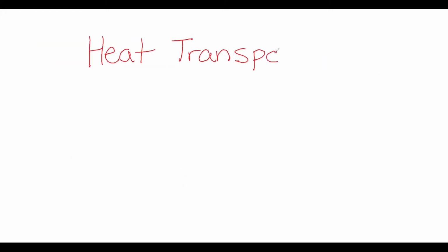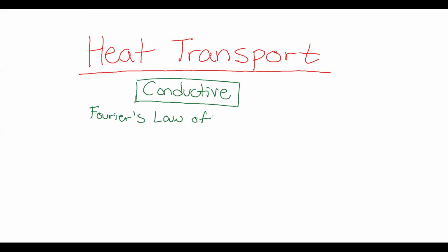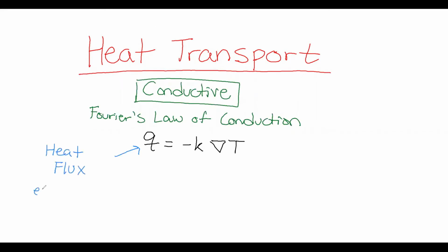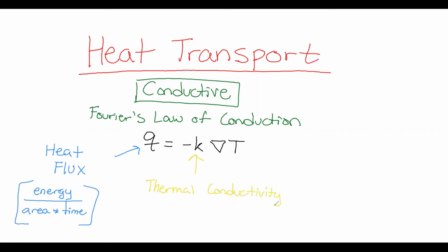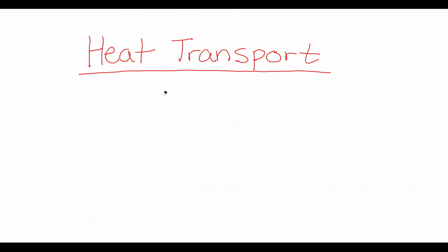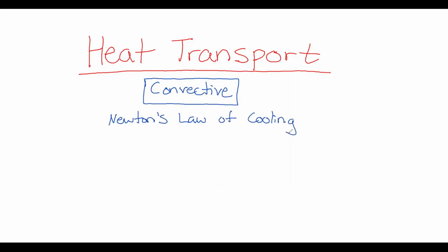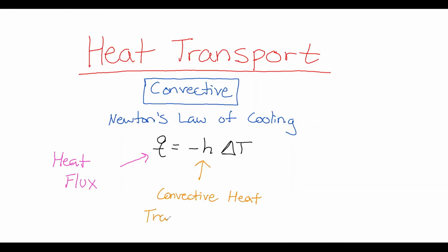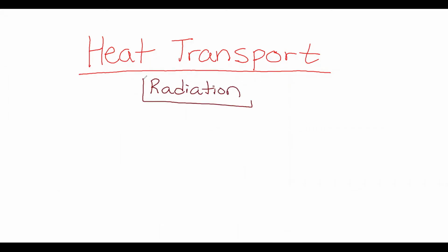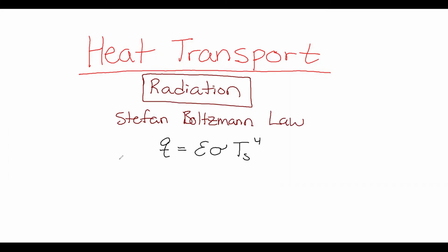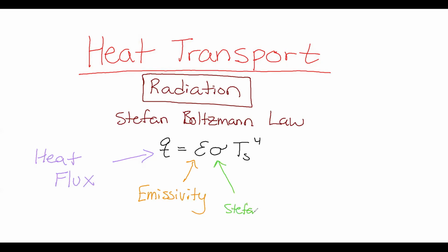The first mechanism we'll explore is heat transport. There are three types of heat transport mechanisms. Conductive heat transfer is the exchange of heat between molecules that collide or touch. Convective heat transfer is the temperature change induced by fluid motion. This fluid motion can be caused by an external force in forced convection or by density differences in natural or free convection. The last type of heat transport is radiation. This is energy emission in the form of electromagnetic waves. Radiation occurs in all surfaces to some extent. Thus, radiation does take place within a coffee machine, but the two main mechanisms we will explore are conduction and